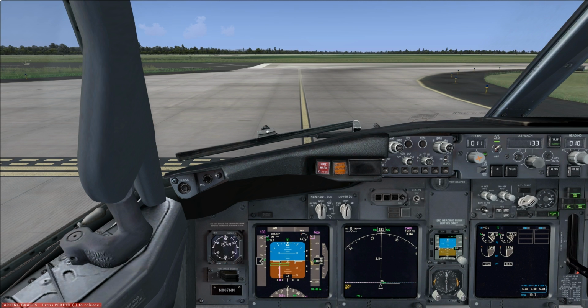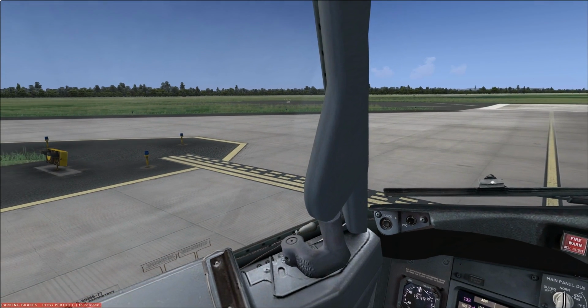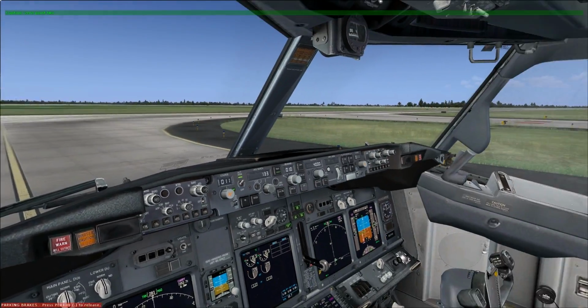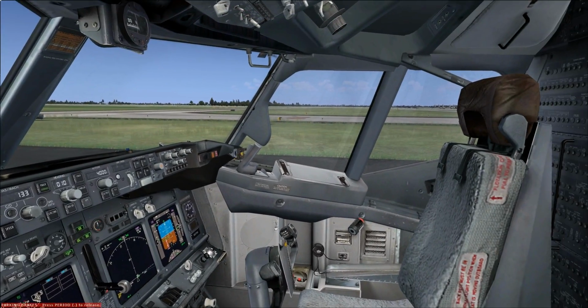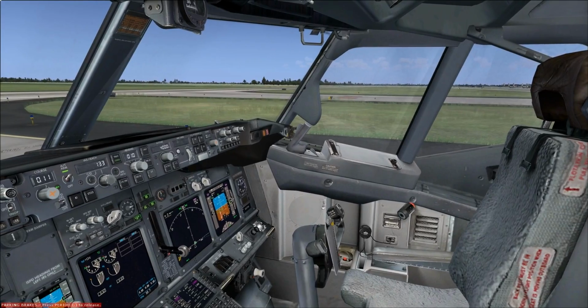You can also suspect wind shear from pilot reports or via the low-level wind shear alerting system, which is a ground-based system located on or in the vicinity of airports. They have different points along the airport field where they put these stations, and they compare wind readings.